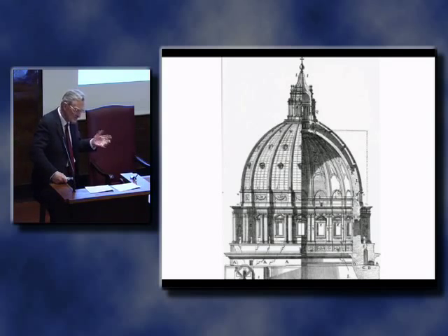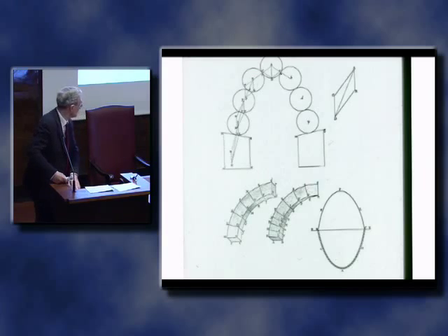dividing the membrane of the dome, if you like, into a two-dimensional arch structure. The cracks had already divided the structure into that sort of grossly exaggerated picture we saw before of orange slices side by side. And Poleni said, let me consider one such slice leaning against one on the other side.